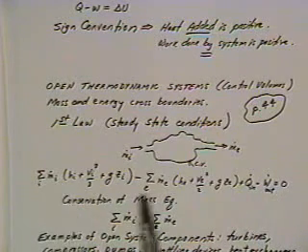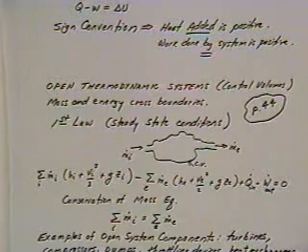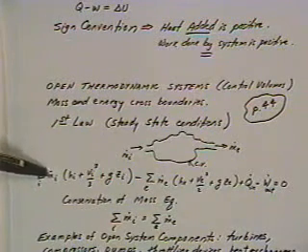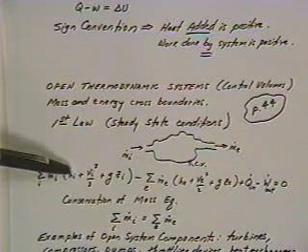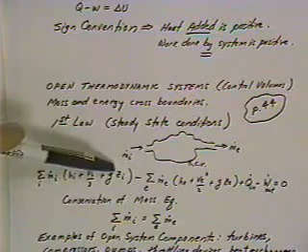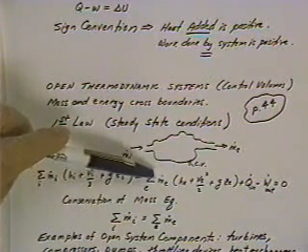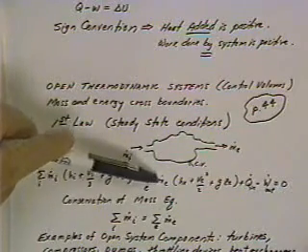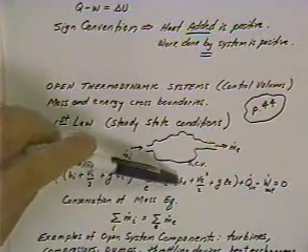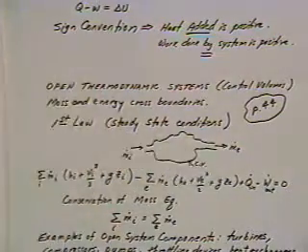This is the general formulation of the first law, where we may have multiple inlets, 2 or 3 or 4 inlets, and we sum up all the mass coming into each of our individual inlets and multiply that by the enthalpy, kinetic energy, and potential energy terms, and we subtract everything that's leaving our system, that's minus the mass exiting, however many exits we have, times the exit enthalpy, kinetic energy, and exit potential energy.